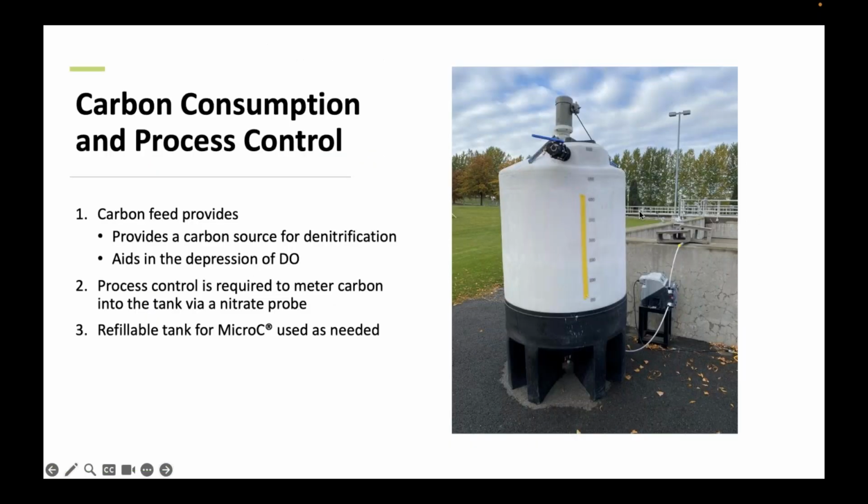And then what we do, because as I mentioned earlier, we need BOD, right? We need BOD to foster the growth of the heterotrophic bacteria that we didn't want in the previous reactor because they take away from the nitrification process. We need BOD available as a carbon source for the denitrification process, right? It actually needs that. And so what we have to do is we have to meter it in, basically.